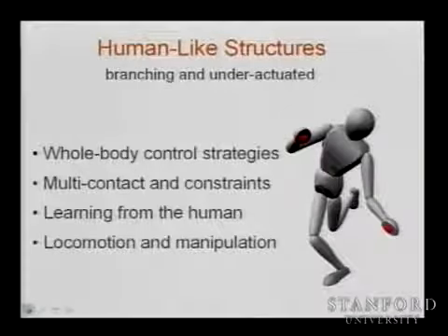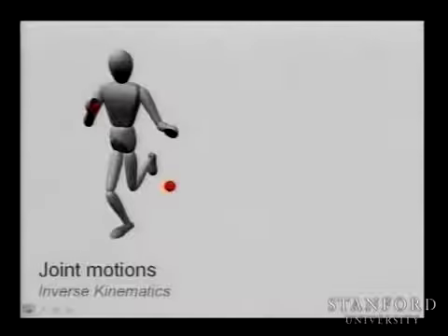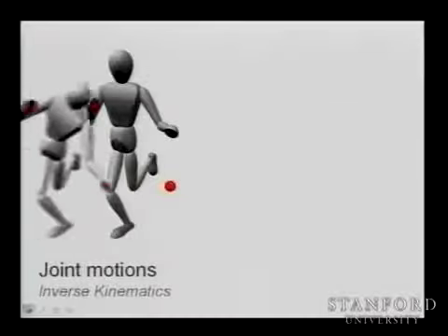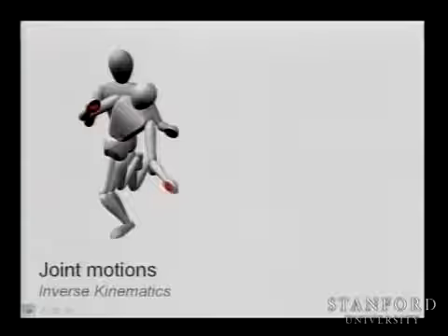We're not talking about contact with one end effector. There are many different points you are controlling. You have multi-contact. You have many constraints. You have a lot of things taking place, and you really need to deal with all of these simultaneously and in a coherent fashion. You cannot pull in one direction without accounting for what is happening in other directions. So dealing with this problem through inverse kinematics is crazy, because you have a lot of degrees of freedom. You do not want to commit to your final configuration before moving, because there are constraints and joint limits and many things that happen.